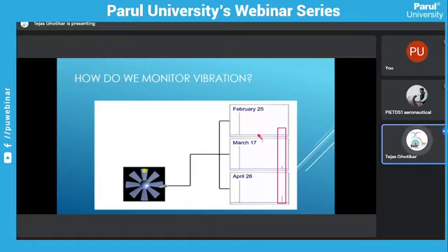After around 20 days, there was the vibration spike. If you see, the amplitude has increased here at the high frequency. And again, after around 40 days, you see the magnitude is now very substantial, right? So with time, the vibration amplitude will increase. If you are able to figure out the vibration at this particular level itself,